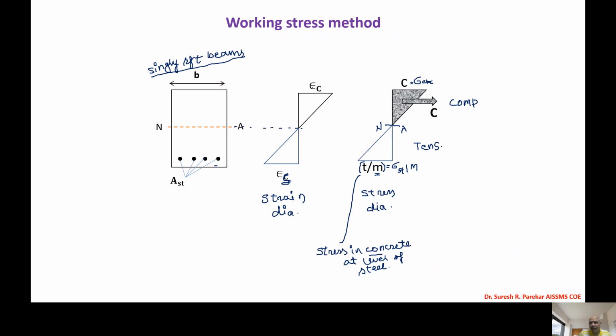Now we have C, the total compressive force, which is equal to B into the area of the stress diagram.